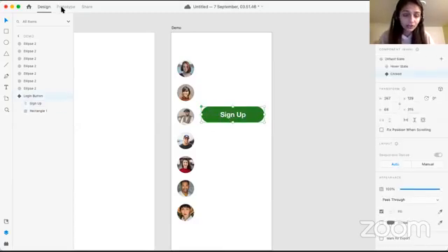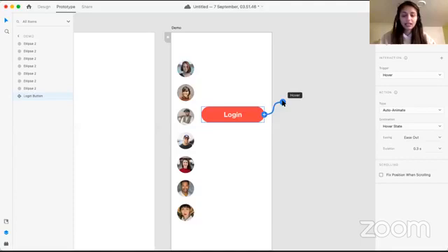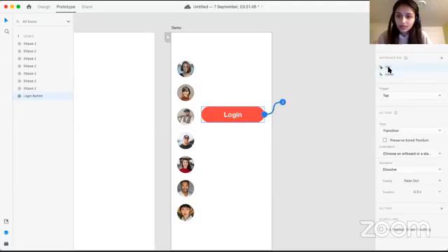So now we actually go into the prototype stage. From the default state over here, I'm actually prototyping the button right now. So right now it is on hover state. I'll click on this one. So this is tap. On tap, it will create a transition. The output that I want to choose is the clicked state, and the animation that I want to use is dissolve. It has different animations: ease in out, snap, wind up, bounce. You can try experimenting with all of them. They're all unique ones, and you'll start identifying the difference. The duration is 0.3 seconds, and I hit enter.